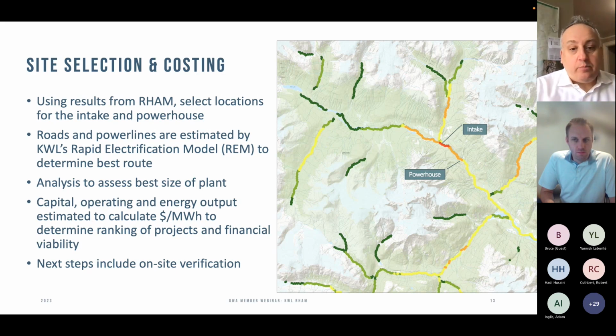In very mountainous parts of the world, that can be really challenging. And then, what's a sensible place for a powerhouse? This might seem ironic, but I've seen powerhouses built below the flood construction level, and that just seems like a really bad idea. Let's make sure we build a powerhouse in a place where it's not going to get flooded out by streams.